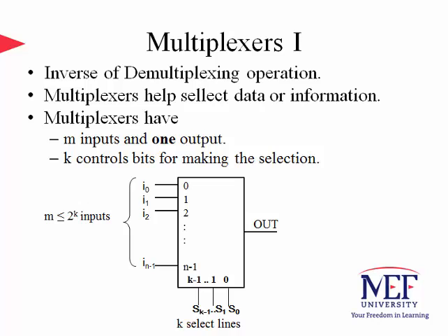And finally, we will touch upon the functionality called multiplexers. A multiplexer is a combinational circuit, and the output depends solely on the input bits. There is no memory in it. Select bits act like location or address information and are used to identify the input that passes through the circuit and becomes equal to the output. So k must be greater than or equal to log base 2 of m. Otherwise, we wouldn't have enough bits to represent each one of the inputs.